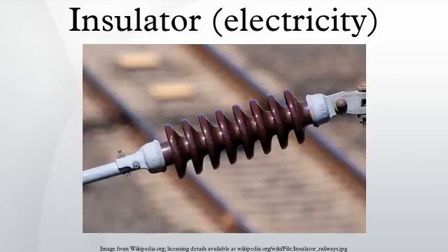In older apparatus made up to the early 1970s, boards made of compressed asbestos may be found. While this is an adequate insulator at power frequencies, handling or repairs to asbestos material can release dangerous fibers into the air and must be carried out cautiously. Wire insulated with felted asbestos was used in high-temperature and rugged applications from the 1920s. Wire of this type was sold by General Electric under the trade name Deltabeston.